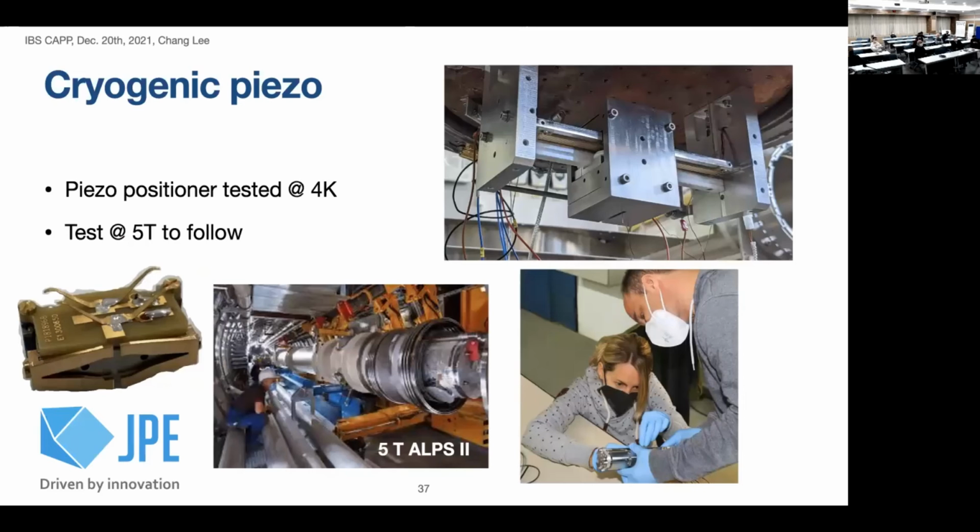And one critical element of all this technical R&D is the cryogenic piezo. The disks will basically sit on this piezo actuator and move along. So far we tried a couple of different models, but not very successfully. But recently we made a successful test with a new piezo actuator. This was developed by JPE. I think I heard that Chang also has experience with it. My colleague Dagmar tested the piezo motor in a liquid helium cryostat, and it was moving very slowly, but well enough. So this confirmed it was operational.